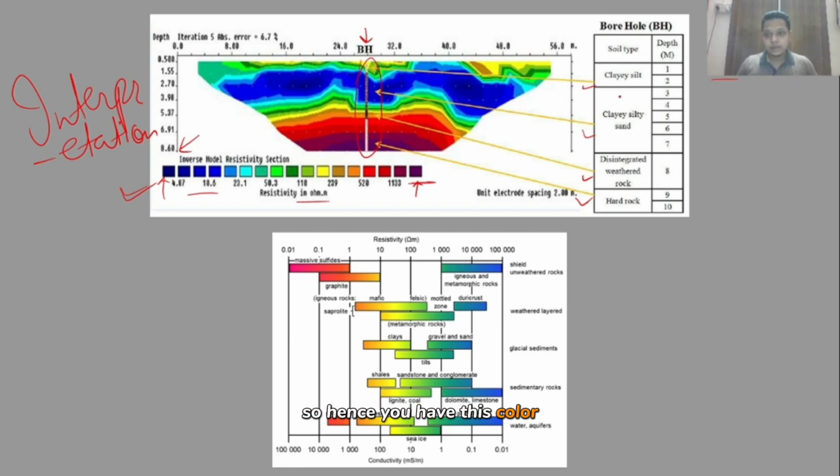So you have this color chart with you, and you can also use different types of charts to show the different resistivity values. Also, you can see that the resistivity variation is quite large, from a very low value of 0.001 ohm meter to hundreds of thousands of ohm meters, depending on the configuration or mineralogy of your rock. So resistivity is one physical parameter which has a wide range of variation. So once you get the resistivity values or the variation in the subsurface, you can very well correlate this chart with your variation, and you can have a very good idea about the subsurface lithology.